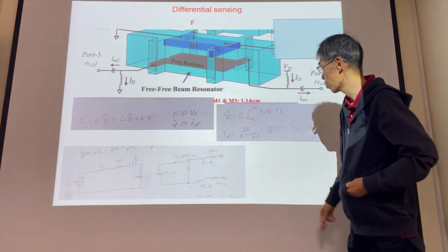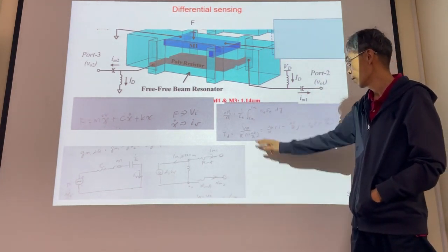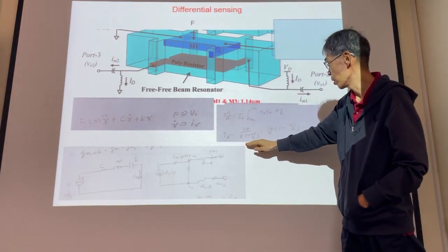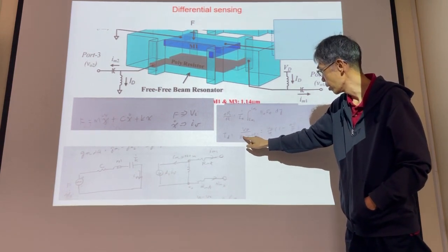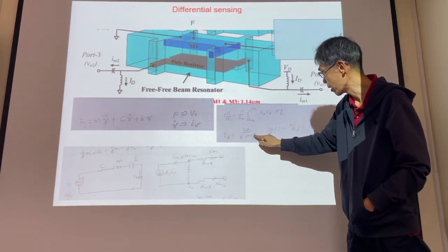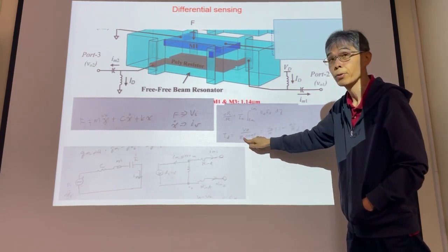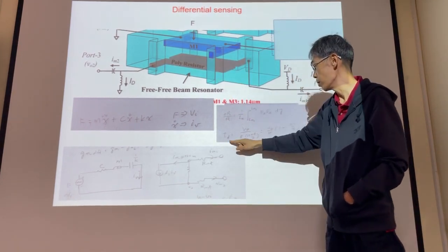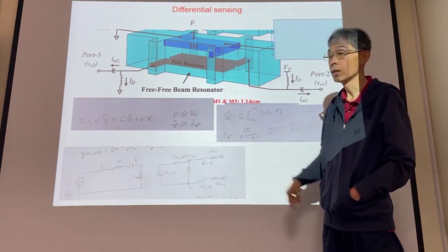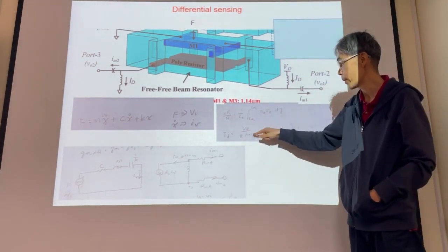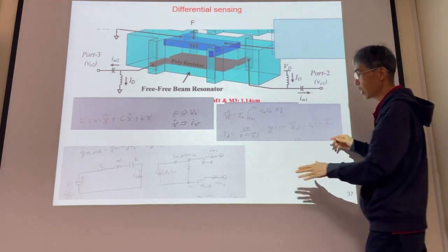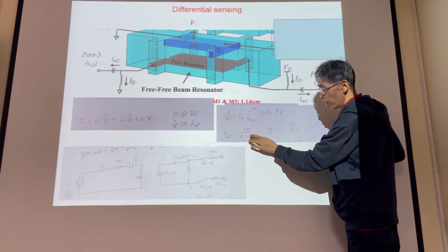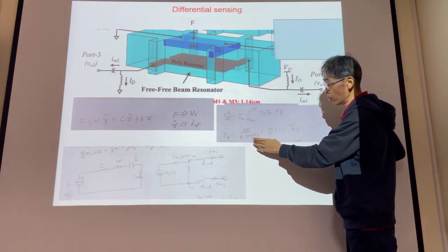Okay, so VD is the supply voltage divided by R. R times 1 is R, R times delta R divided by R is delta R. So this one is R plus delta R. So VD divided by R plus delta R is the DC current ID, equal to VD divided by total resistance. Then VD here, and R times 1 plus delta R divided by R. Delta R divided by R is a small number compared to 1.